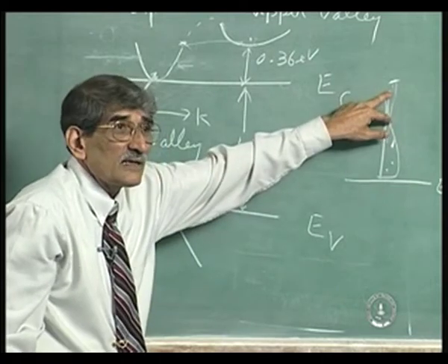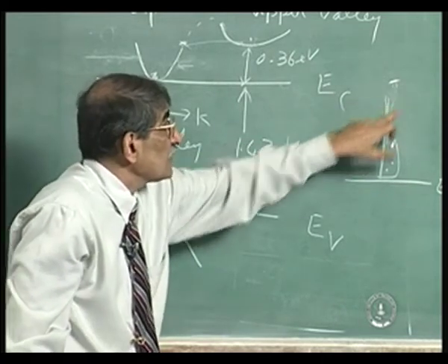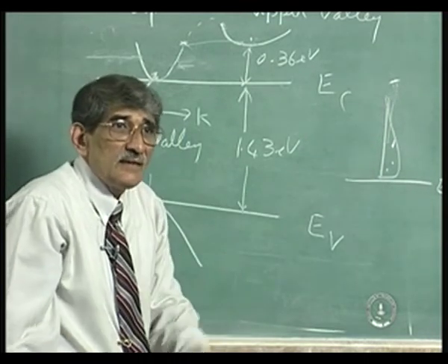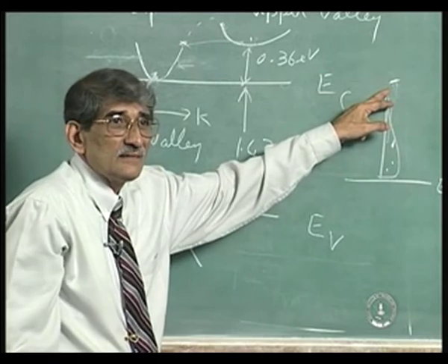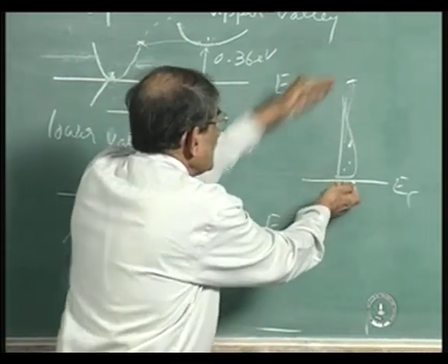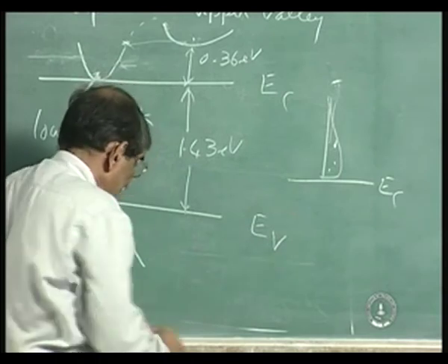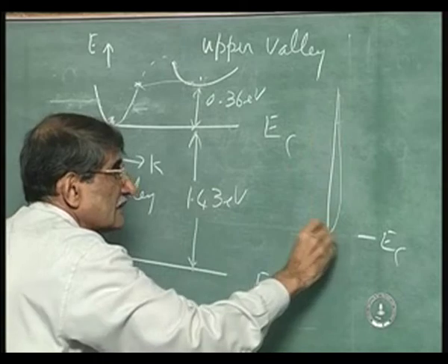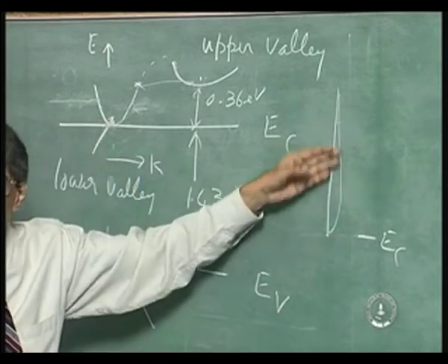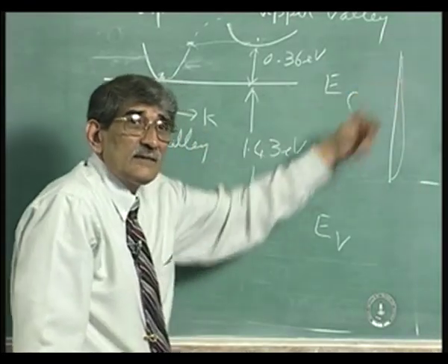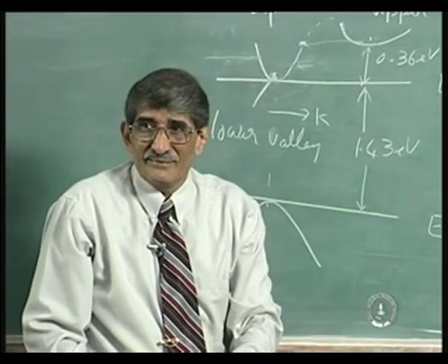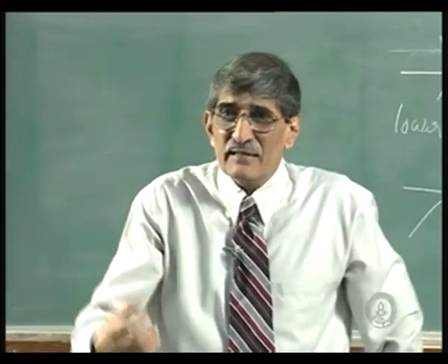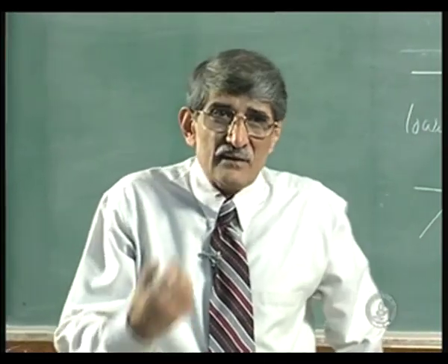So this will be a hot electron, which does not obey the law corresponding to room temperature, but you can still write those equations taking a temperature corresponding to that. If I distribute the whole thing up there, you get a distribution which goes up beyond thermal equilibrium. Then you have to change T to Te. That is what you are doing: you write the equations corresponding to the temperature of the electron, that is, the higher energy.